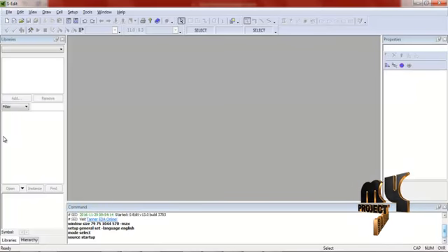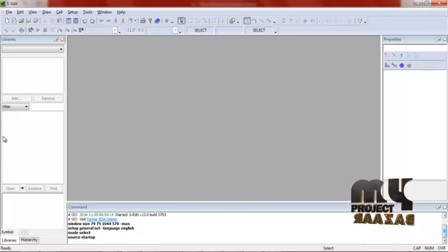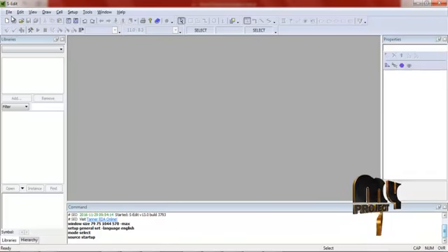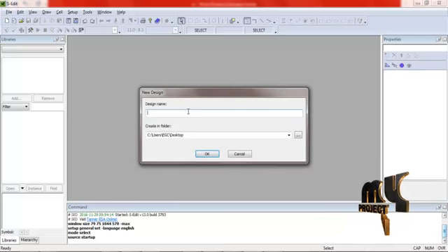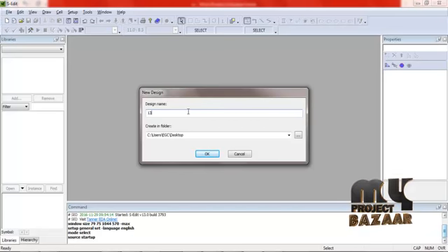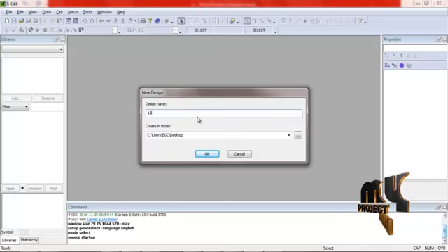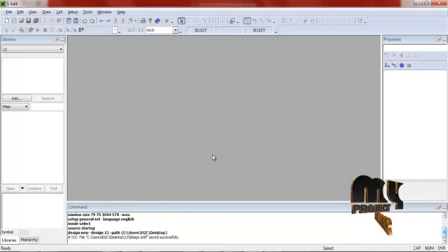Now we are going to discuss the running procedure of our product. In our product we are using the Tanner EDA 13.0 version tool. Now open the tool window and create a new schematic, using the file menu to create a new design. In order to assign the design name and the desired path, assign the design name 13T SRAM. After assigning the design name, click OK to continue.